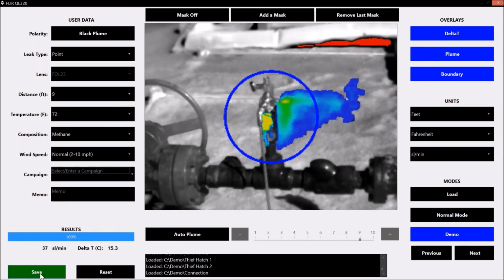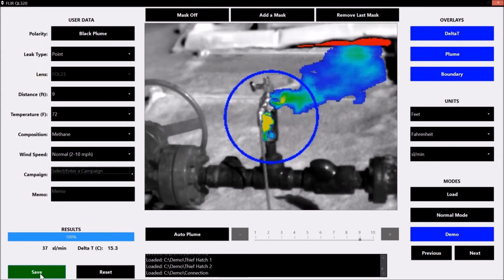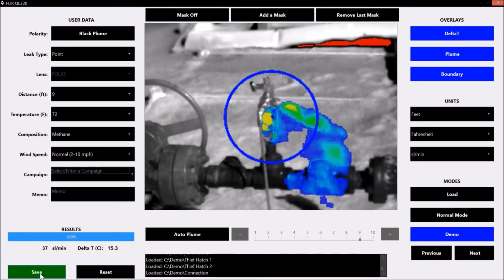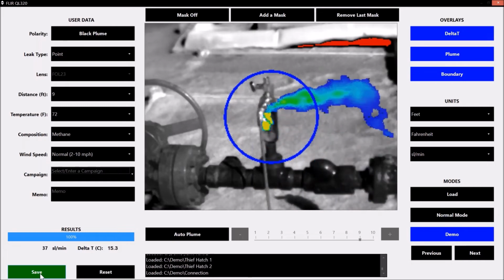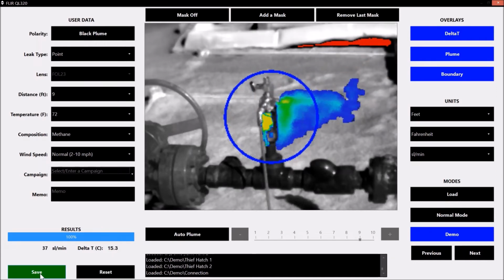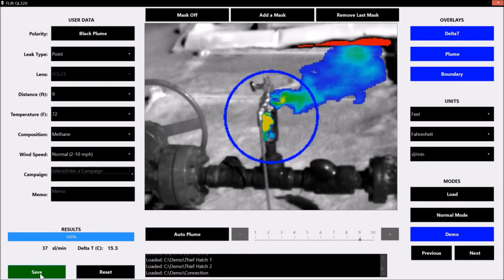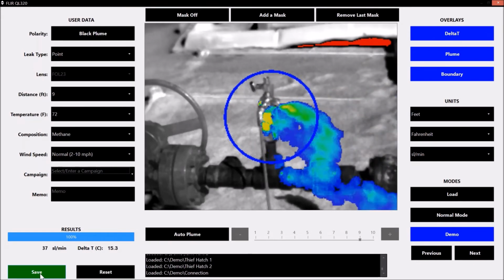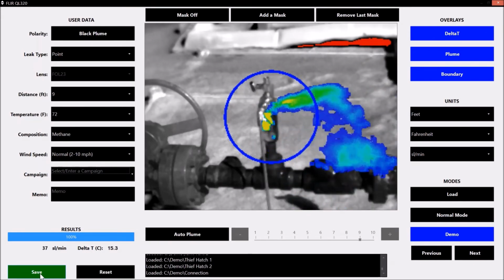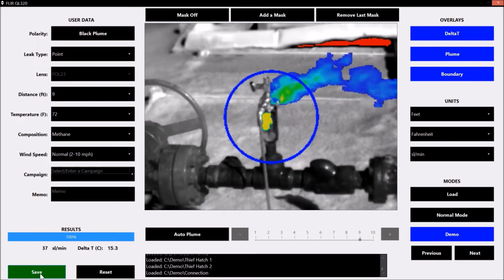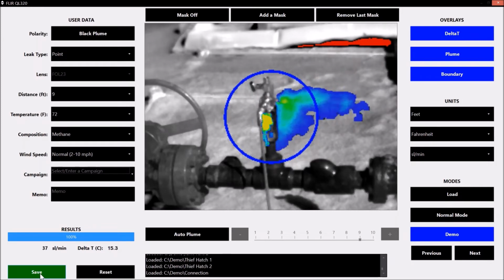And the algorithm will also change. Instead of 21 or 22 standard liters per minute, it's thinking that I'm further away, so that leak looks bigger, because the QL320 thinks that it is bigger, even though you're just closer to it. It's bigger, just as if I were to walk up to an object and stand 1 meter away, it would look big, but if I stand 5 meters away, that object looks smaller.